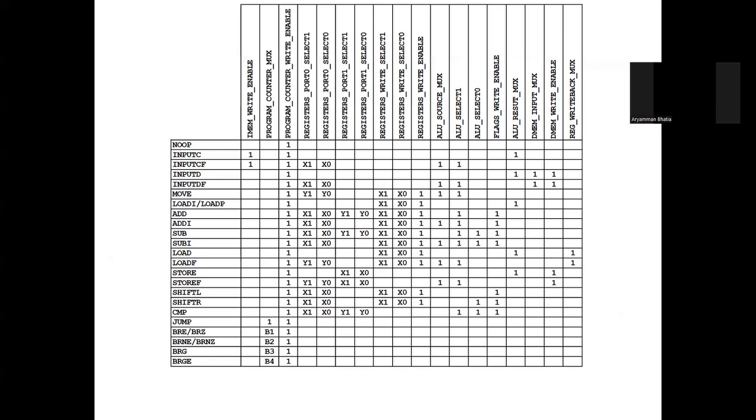So when the user writes in assembly to do this instruction on this particular register, it converts the instruction into the operation code, and it maps the register into these x1, x0, y1, y0 bits to execute that onto the register, right?